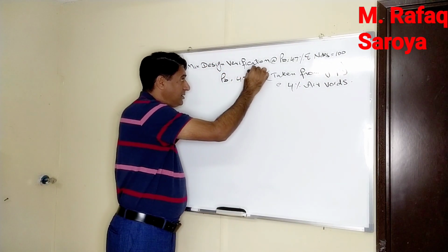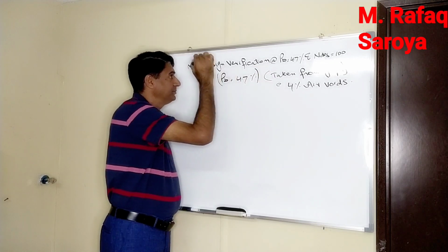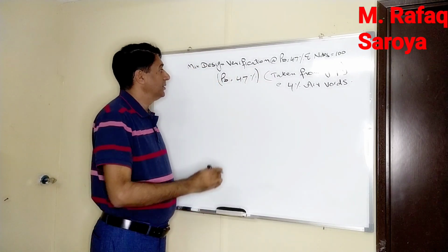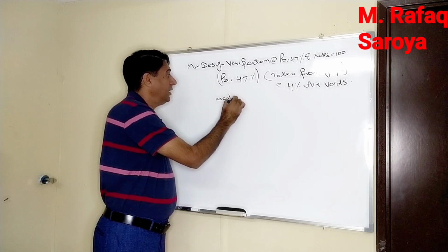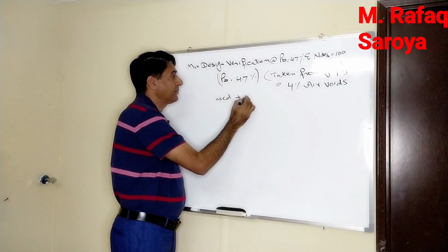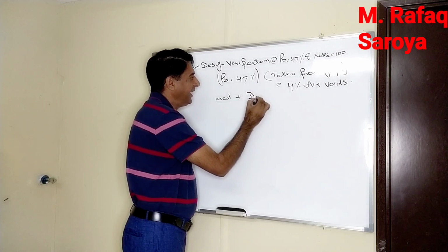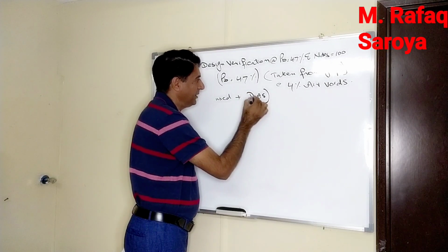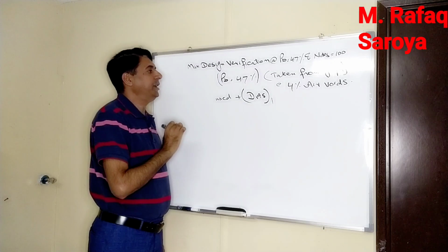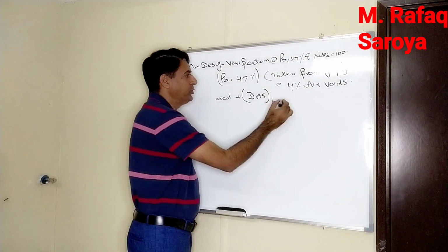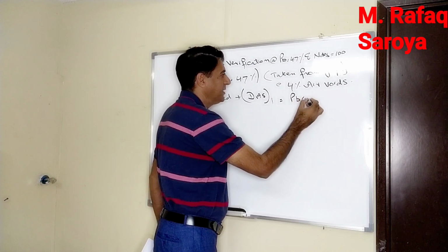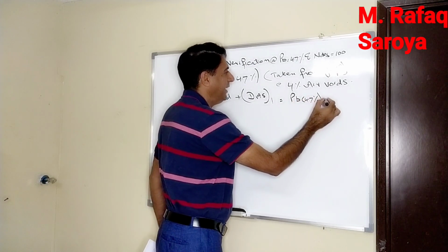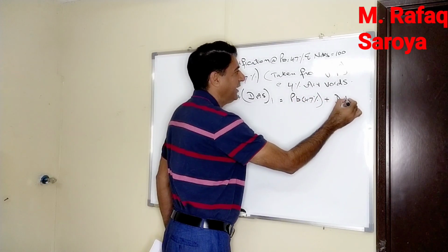This selected amount of the binder is being used along with design aggregate structure number 1. It means I will use the combination of this Pb, which is 4.7%, and then aggregate from this design aggregate structure number 1.